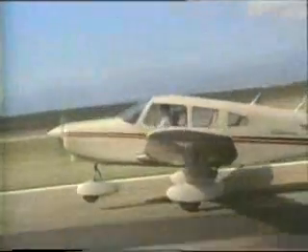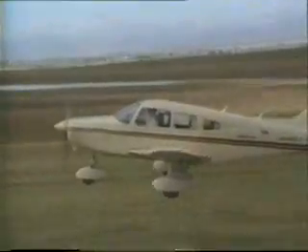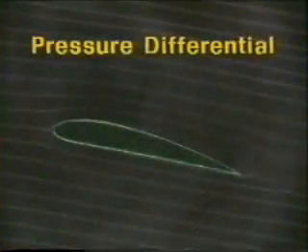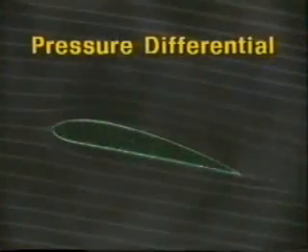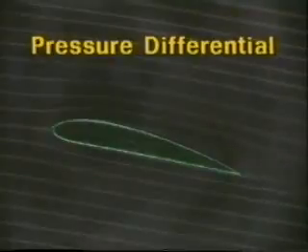Aerodynamic discussions typically stem from conversations of the creation of lift and the relationship of the forces acting on an airplane. However, in order to better understand these forces, you must be able to measure and calculate them as they apply to aircraft in flight. The pressure differential between the upper and lower surfaces of a wing is the catalyst of any lift analysis. This pressure differential multiplied by the planform area determines the wing's aerodynamic force.